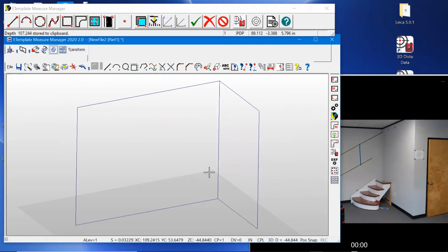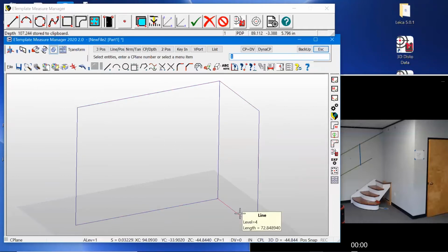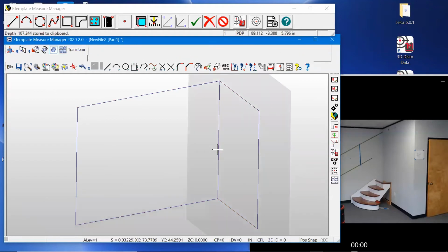So now let's just say that I want to have some connecting points on, say, this wall panel here. So if I want to do that, then I need to be able to establish that as my working plane. And I can switch to that for a plane. As so. So now this wall has become my working plane from the floor. And I want to go and take a series of points. And I'm going to take these as 3D points.